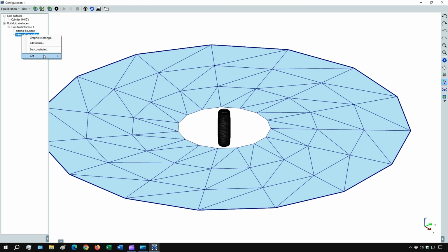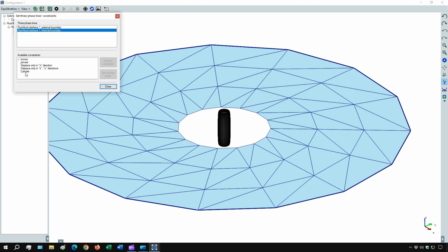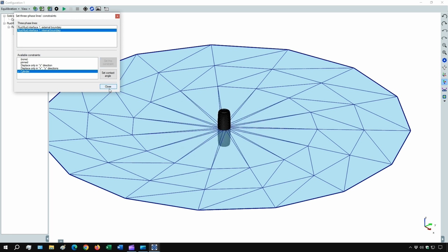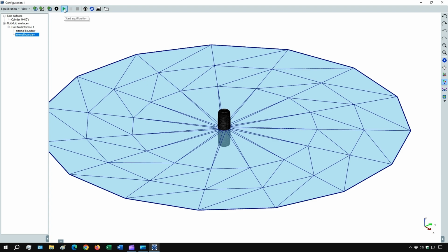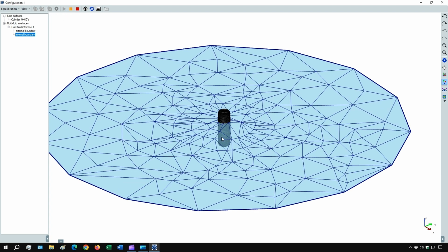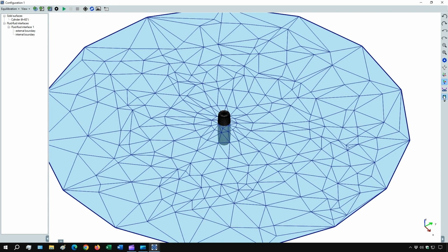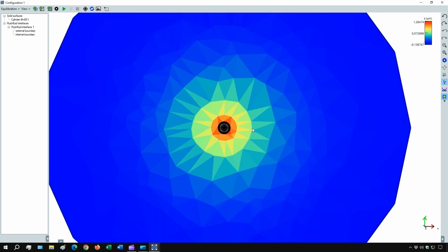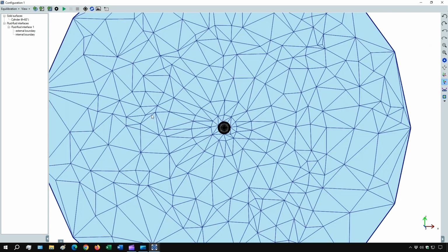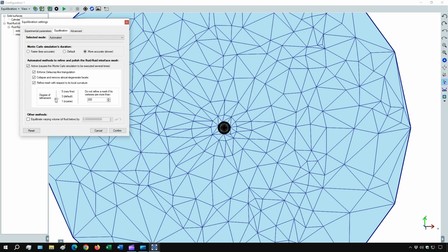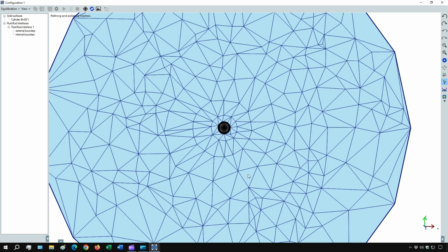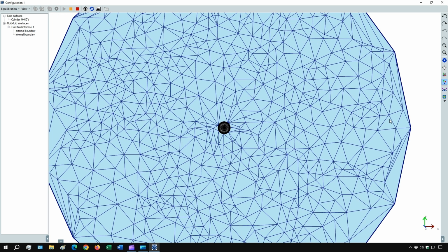Let's now set the cylindrical particle as constraint for the fluid interface inner boundary to calculate the interface's equilibrium shape when the cylinder is adsorbed at the interface in this orientation. As you can see, at the equilibrium, the interface forms a capillary monopolar deformation near the cylinder, induced by the cylinder's contact angle. Let's now run another equilibration, allowing a finer refinement for the mesh, using this as initial mesh for the fluid interface, to find a more accurate equilibrium shape.